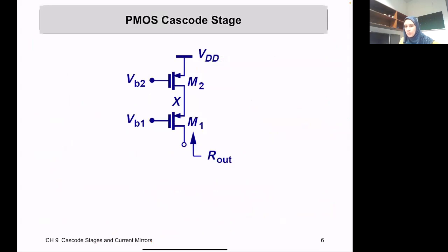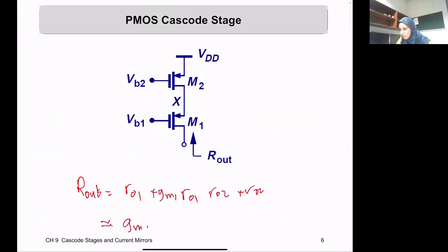Okay, now we can also again have the PMOS give us the same output impedance using the cascode. So it will be exactly the same. Now you just need to make sure that, let me write, GM, almost GM1, R out 1, R out 2. Now you need to remember that the GM is of the one that you are first looking through.